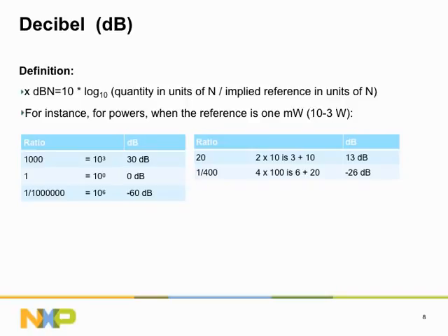This practice is common when figuring power, gains, and losses through long chains of components. So engineers will always babble in terms of dB, dBm, dBc, etc. To know how many dB some property is, we need to know how many zeros were added to the number in the linear, math domain. Then, to get the number of dBs, we multiply by 10. For instance, if a signal gets amplified and becomes 1,000 times larger, then 3 zeros were added to its value. This 3 gets multiplied by 10 to get 30 dB.